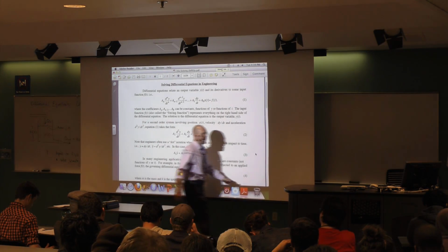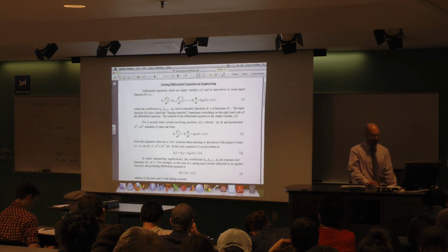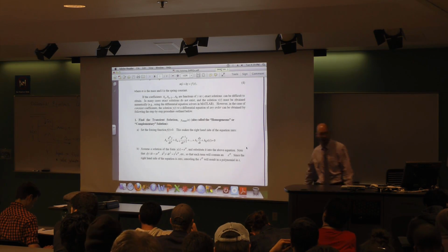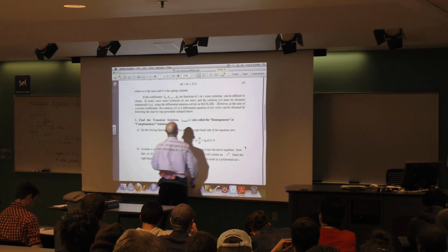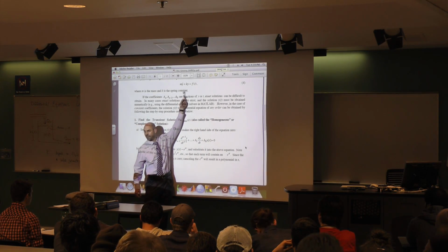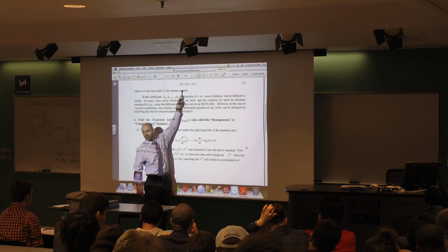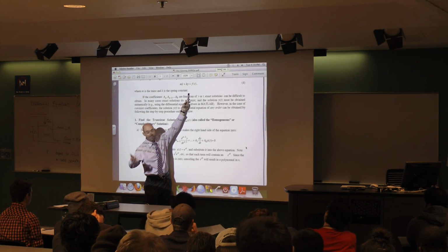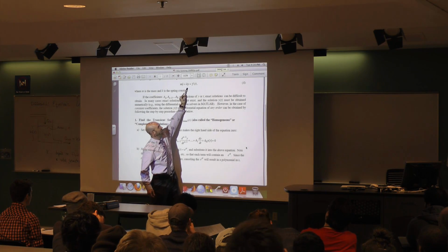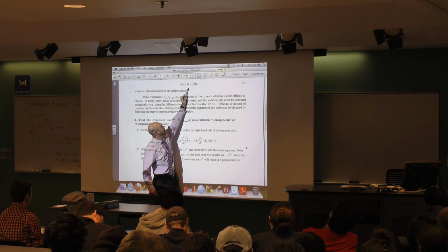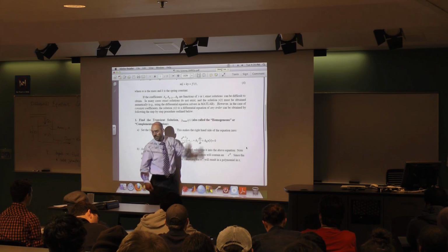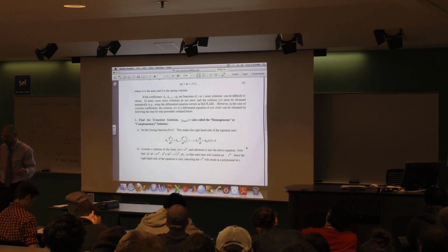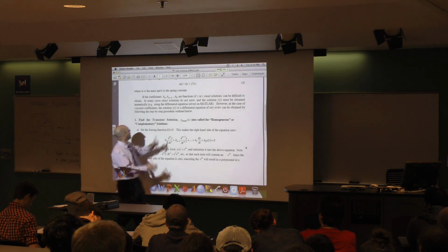So back to the dynamics problem. We've talked in here already about springs and masses and such, and you're already doing the lab on this. And here's the governing equation for a spring mass system. M's the mass, y double dot's the acceleration, right? So this is force equals ma. Here's the ma, here's a spring force, k times y. Here's the forcing function, f of t. So it's just a statement of f equals ma when I have an oscillating dynamic system. And that's a classic example.